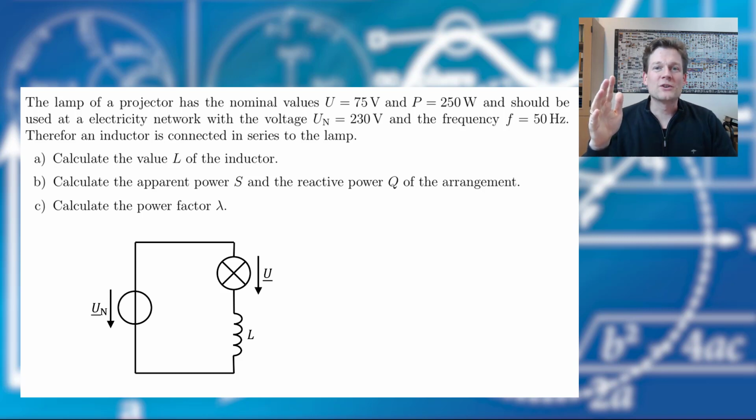And of course we could use a resistor, but a resistor consumes active power and we have to pay for that. And therefore we just connect an inductor in series, because an inductor consumes reactive power and that is for free.